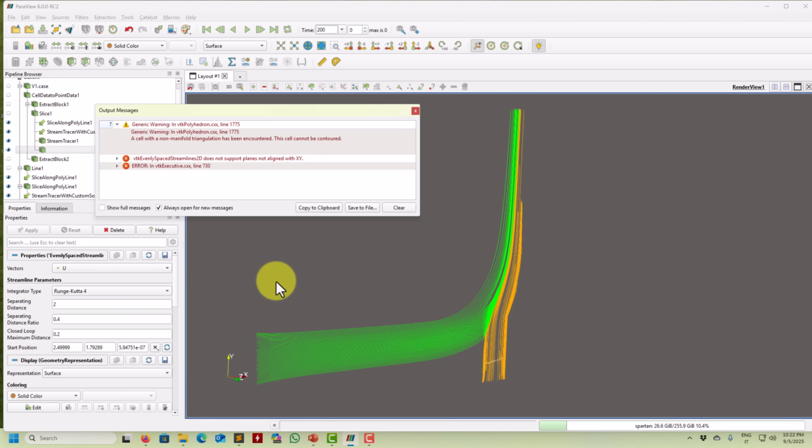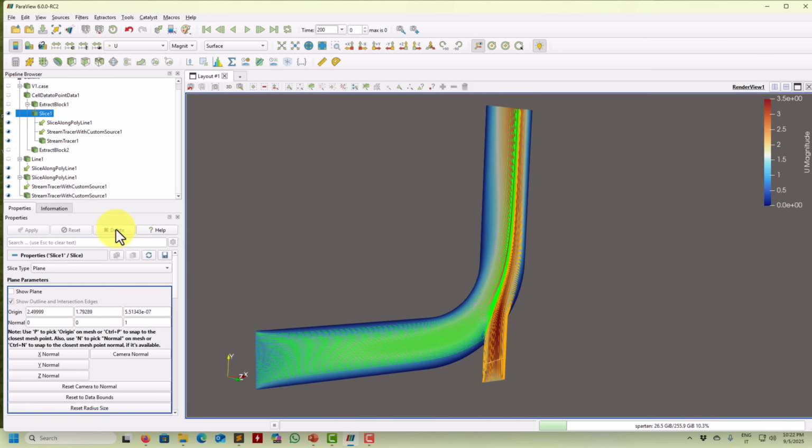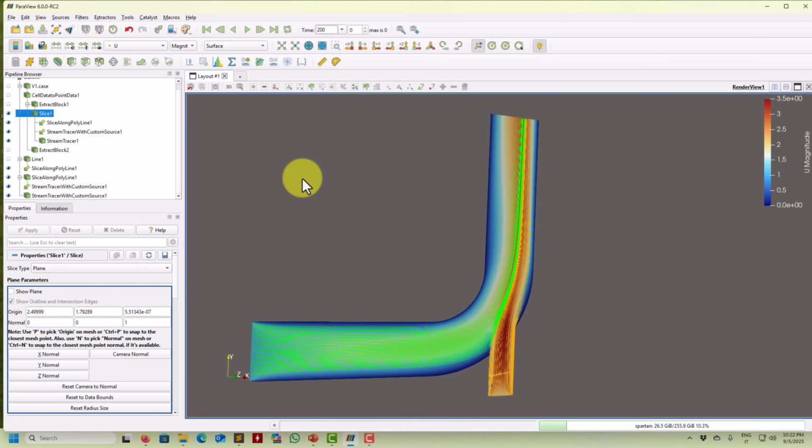So it's tricky to get it to work, so I don't use it. The way I do it is how I showed it, but just in case you're wondering, you have that one exclusively to constrain a plane in XY. Usually 2D data will work, and 3D also will work, but you need to have that specific plane perfectly at 0, and you need to have the seed coordinate. It is tricky to get it working. Okay, so this is it.